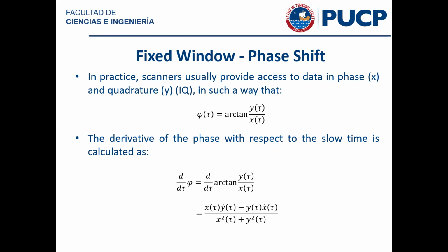So that's the reason why people were smart and wise enough many years ago to say, I'm not going to deal with this junk. I'm not going to digitize the original signal. I bring it to baseband so I can digitize it at a lower sampling frequency. And there is a very nice thing about this.